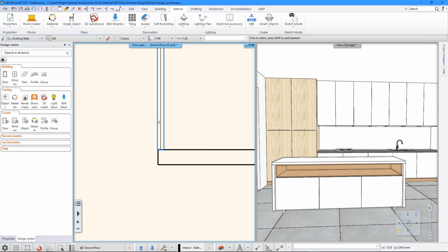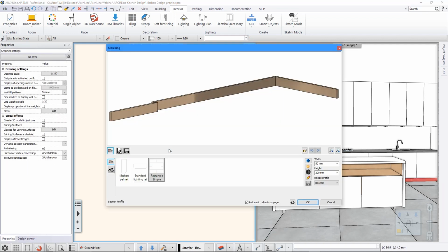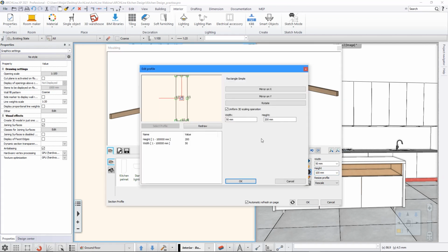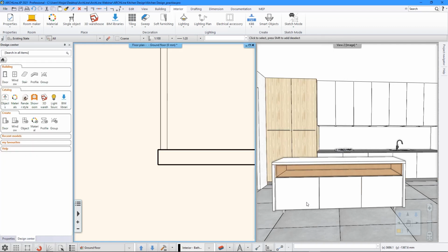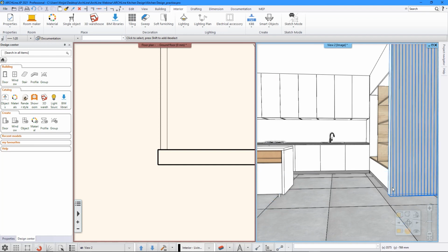So you can see the plinth is actually a bit out of the wall surfaces. So I'm going to edit it so that it's slightly inside the wall. So I need to change the height of the plinth to 100 and change the reference point for my plinth to the bottom right corner. Last but not least, change the materials to dark gray. And then now you can see the plinth over here that's created. So it's somewhere a bit inside of the wall, so it's not protruding out of the cabinet.